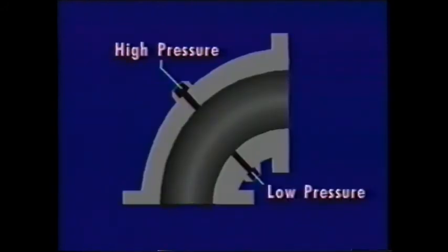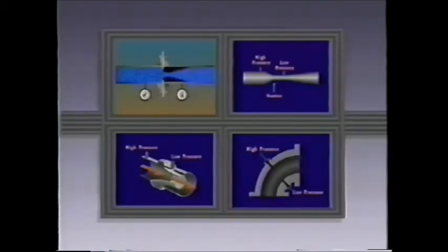The flow of fluid through a curved path, such as a piping elbow, also generates a differential pressure proportional to flow. An elbow tap flow meter is based on the principle that the acceleration of the fluid around the curved path creates a centrifugal force causing the pressure on the outside of the curve to be greater than the pressure on the inside of the curve. Flow measurement loops making use of differential pressure measure volumetric flow. If mass flow measurement is needed, the instrument system must also measure fluid pressure and temperature.